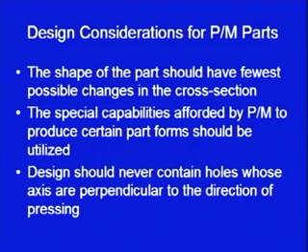The design should never contain holes whose axes are perpendicular to the direction of pressing. This will be explained with the help of a diagram, which will make it absolutely clear that the axis of the holes should never be perpendicular to the direction of pressing. Otherwise, the roundness or circularity of the hole that we get may be disturbed.